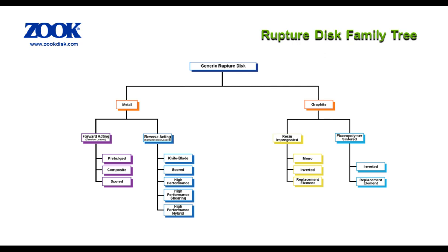Extra care needs to be taken when selecting reverse-acting disks, as some designs are not fail-safe. Incorrect selection or installation can lead to a dangerous situation. Reverse-acting disks tend to be more susceptible to damage and are typically designed for either gas or liquid service.